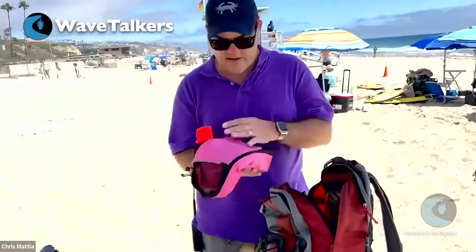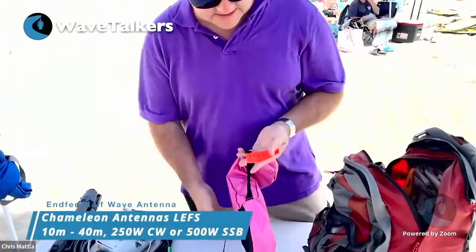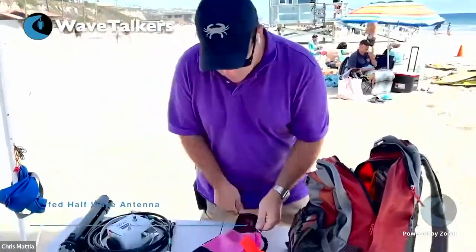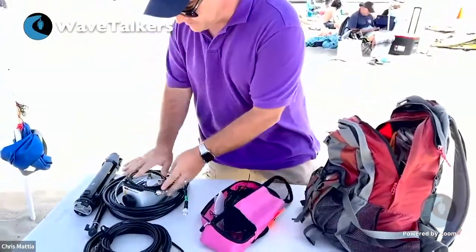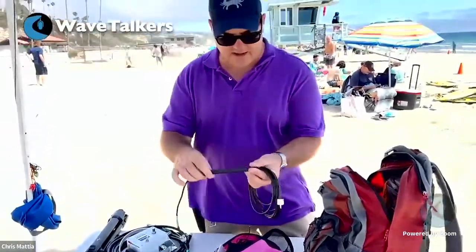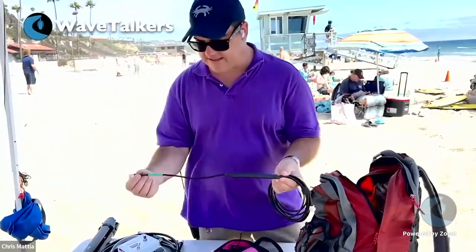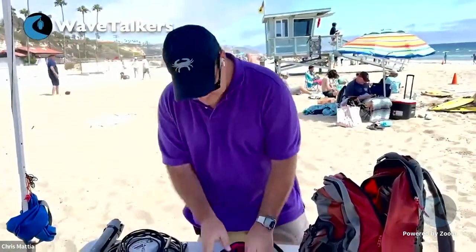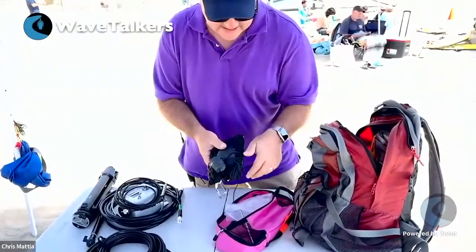I have a few others here. This one here is also by Chameleon. This is the LEFS antenna. It's good for 6 to 40 meters. It's a really small wire antenna. There's a little short piece of coax, and actually this one goes with the F-Loop, but you can use it with the other ones. It's got some toroids or some ferrite beads in line to act as a choke, so that works really well. And then the LEFS antenna, there's a length of line here that you can use, like if you're out in a location where you got trees or something, you want to pull it up, you can use that to be able to hoist the antenna.